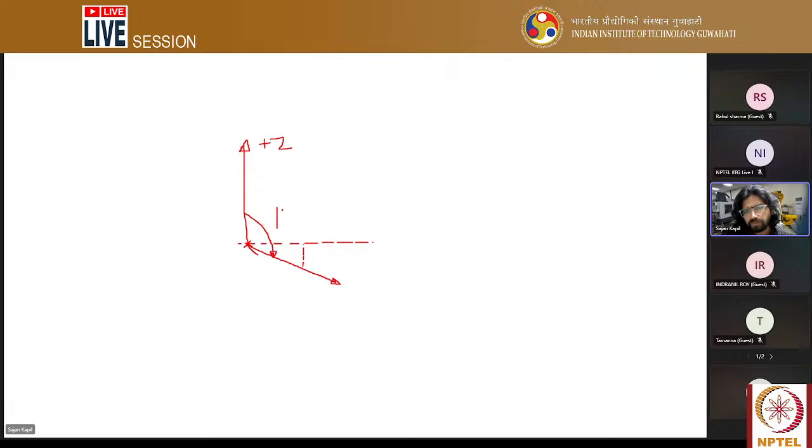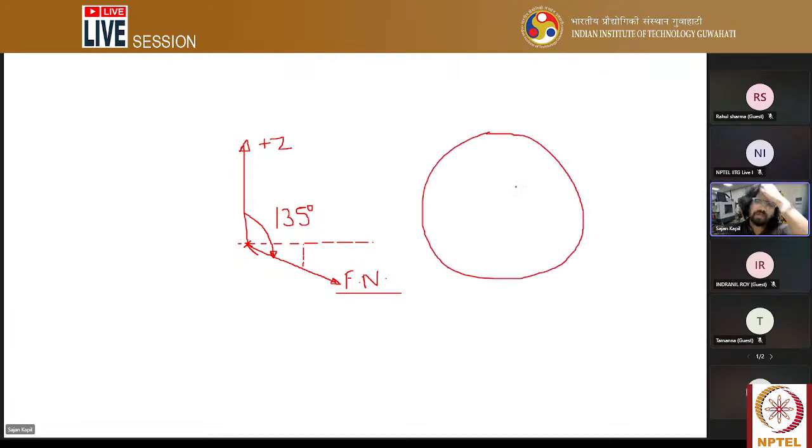So the question should be written as: if the angle of the facet normal is more than 35°, then how many triangles require support? Then you can select the correct option. As this is a sphere, we are talking about a quarter of it, because this is 45°, this is 90°, this is 45°, this is another 45°, correct? So the portion that will require support in this case is this one. This portion will require support.